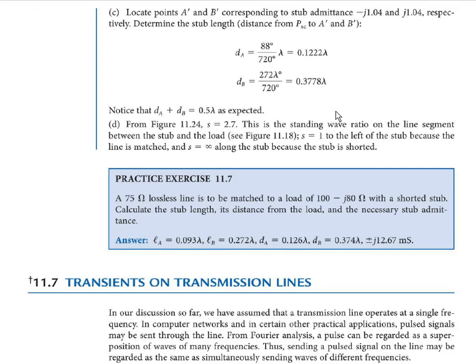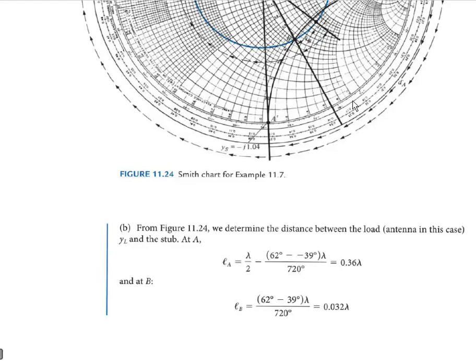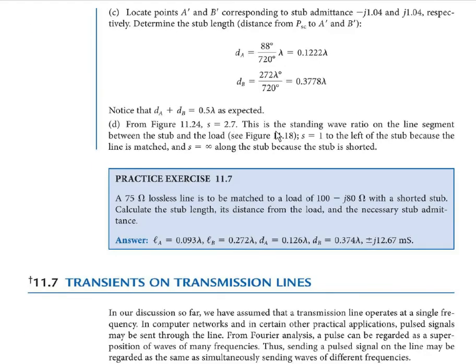So that is the possibility of cross checking these two distances. Then we need to find the VSWR. That's our fourth question. We need to find the VSWR. So VSWR means the value where we get this VSWR circle meeting point on the x-axis. So that is here 2.7.